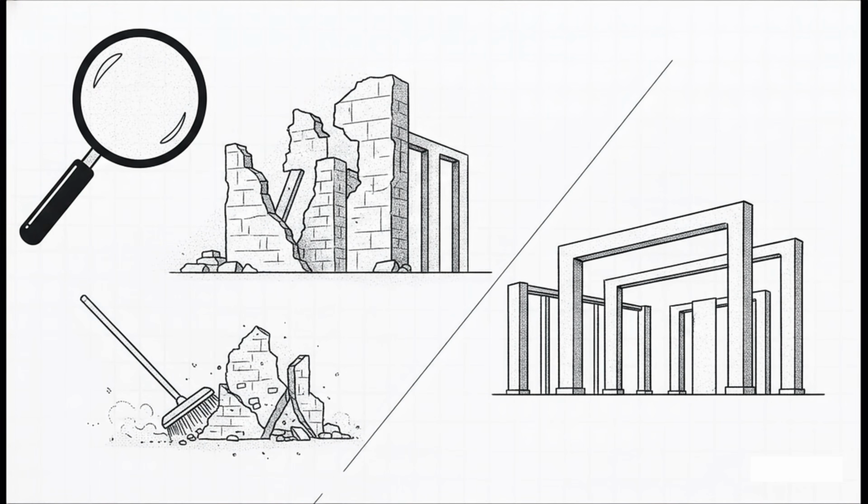The real beauty of Navisworks is how it pulls that deep metadata straight out of Revit. Over in the Find Items window, you can group elements by very specific Revit properties. Imagine you're on a massive, complex renovation project. You can search for the property phase, set the condition to demolished, and instantly grab all the demo scope across the entire model. With just one click, you can hide all of it. It instantly cleans up your visual workspace, so you're only seeing the new construction.